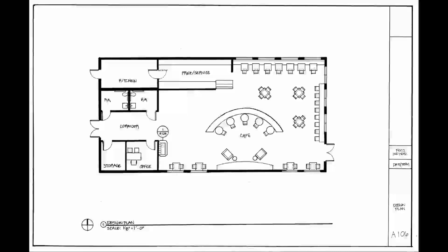So it looks similar to an elevation tag, but it's a slightly different symbol. The top half of the circle has a number, and that refers to the drawing number. So it's drawing number 1. And we are going to look at sheet A104 to see more information about this object. So that's the annotation there. So drawing 1, sheet A104. That's where we're going to hop over next.